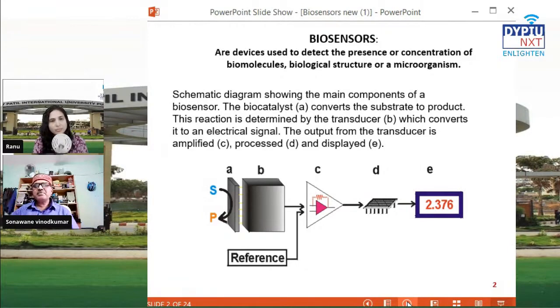The current will be measured in milliampere or microampere, and this will change with the concentration of the solute in the solution. If the salt is more, the current is more. This is how we can sense sodium chloride in water. If you take distilled water, we should not get any current in the meter.